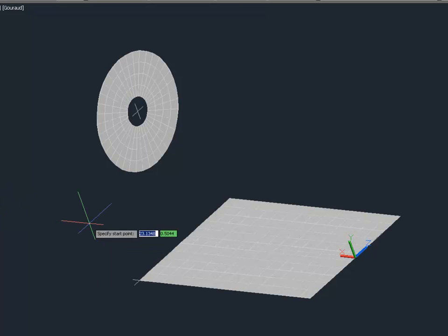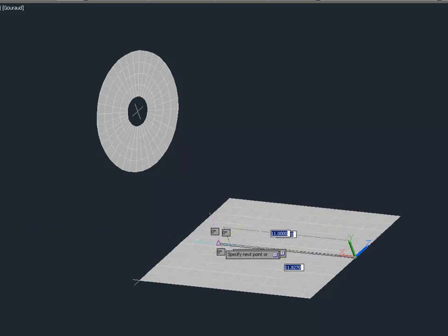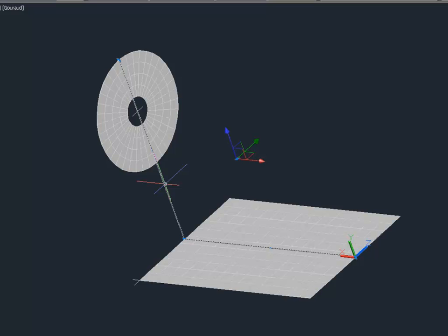and define another line. This time I'm just going to make it a straight line. I'm going to come down along the plate and up through the center of the disk, and I have my construction line now. If this had been a VCHP, I should have been careful to start that operation at the cold end, so that's where the reservoir would be placed. This is not going to be a VCHP, so I don't have to worry about that now.